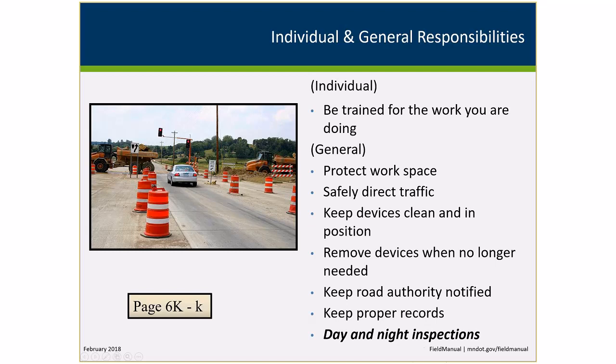That's one of the key ways that we can help make sure our temporary traffic control is safe for both the traveling public and our workers. We don't want to get put into the case where we set it up at the beginning and don't really pay attention to it, because things happen. Traffic may behave erratically and we don't necessarily notice it, and we really need to make sure we do good inspections as the project progresses to make sure that the traffic control is doing what it needs to do to keep the workers and the driving public safe.